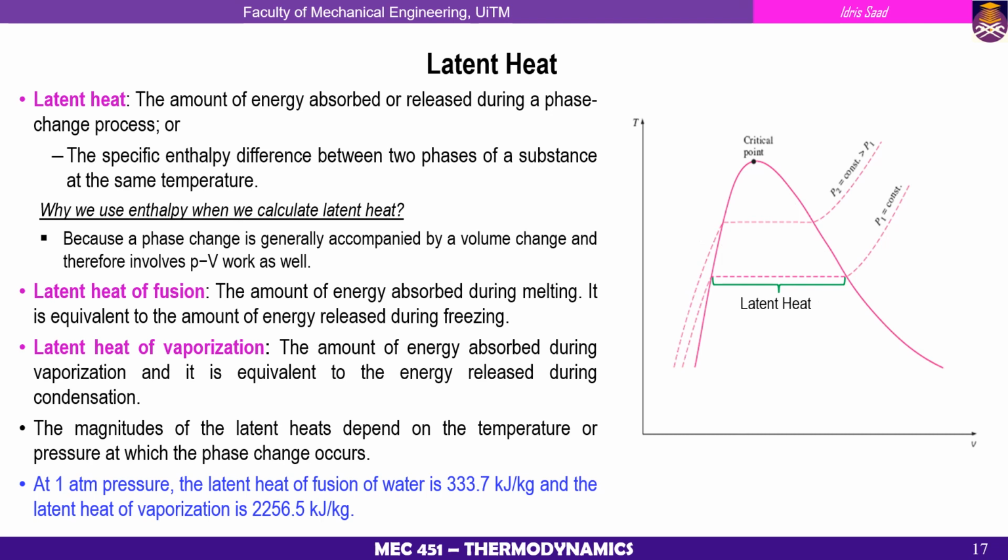That is because the difference between the molecule arrangement of the solid and liquid is relatively small, as we see on the microstructure, or what we call the molecular arrangement of the solid and liquid. But the difference in molecule arrangement between liquid and gas is relatively large, since the gas can move freely without any hesitation within its container. That's why the value of the latent heat of vaporization is much higher than the latent heat of fusion.